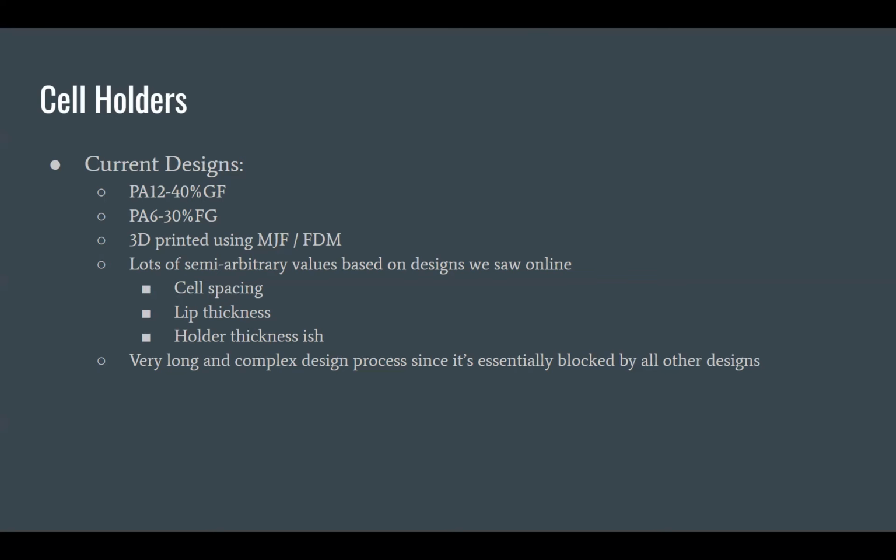Yeah. And so at least from the preliminary math that we did, the breakdown voltage of air is very, very, very high. And especially considering, even though these segments are at 84 volts, that's nowhere near the 600 volt peak of our battery pack. So we do generally take a little bit more care when we're separating the full voltage of the battery. But from my understanding, there's no direct rules. It's more of just follow good engineering disciplines. And if there are manufacturer recommendations, then follow the manufacturer recommendations.